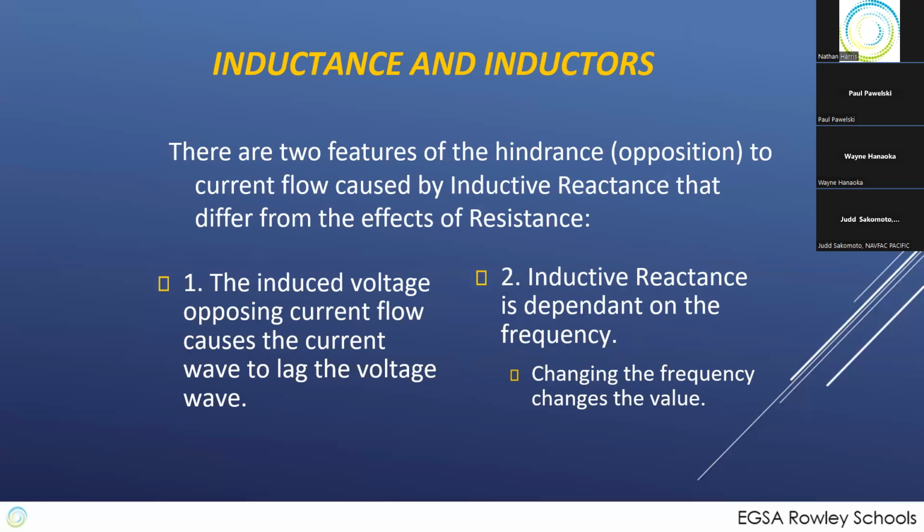So the two things to this opposition: the induced voltage is caused by the current wave, which causes the current wave to lag the voltage wave, and the inductive reactance is dependent on the frequency. If you change the frequency, the ohms of inductive resistance change. And the same is true of capacitive reactance. What that means is if you use a higher frequency, a smaller inductor or capacitor will do the same job.